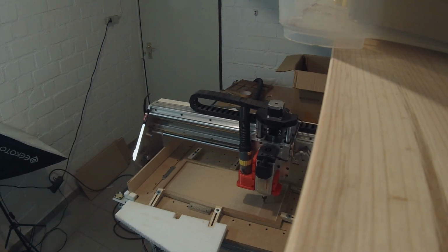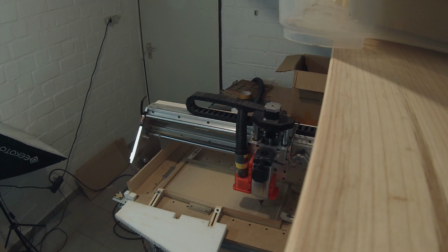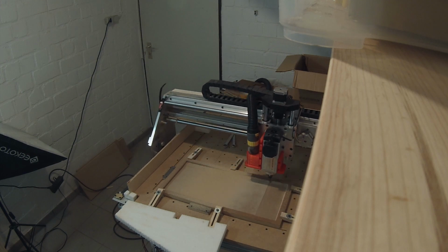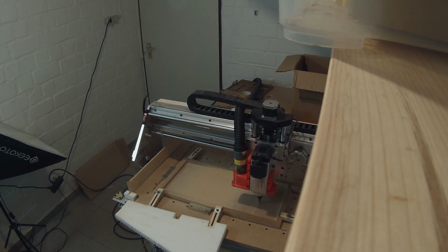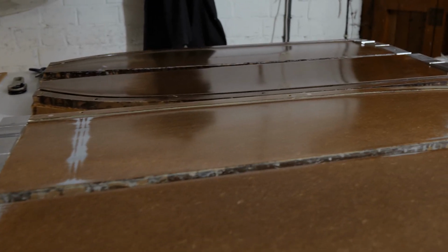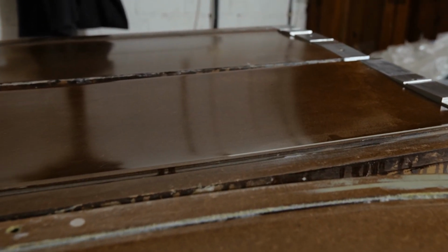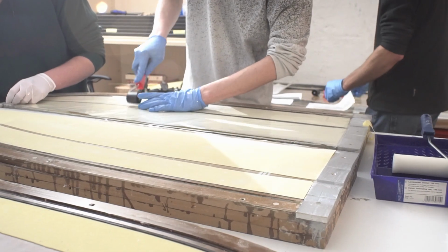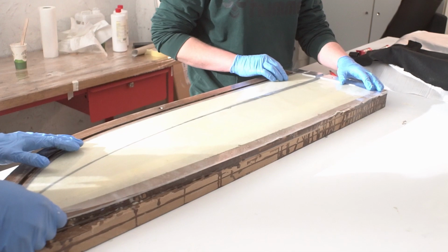after a failed attempt, which was very useful since we were forced to start over many times after running into various problems. One big cause for trouble was our CNC router, which was simply not up to the task of operating for up to 5 hours continuously, and had to be upgraded in various ways. We eventually were able to machine all 4 molds, and the first attempt at laminating a wing showed that the molds were working fine. But at this point we had not enough time left to work on the difficult process of laminating these composite wings.